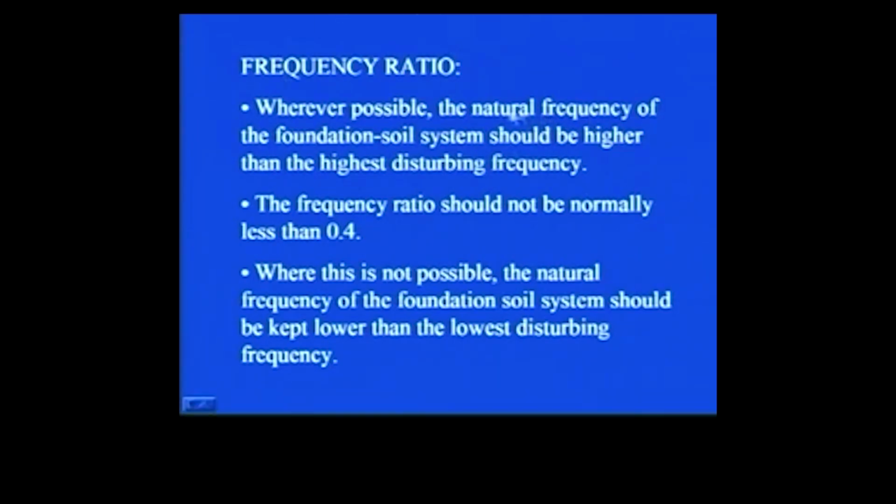So, the natural frequency of the soil foundation system should always be kept higher than the highest disturbing frequency, because if it is more than the highest disturbing frequency, obviously the resonance condition will never be reached.